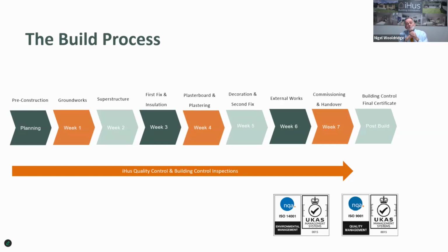green credentials. You'll be very pleased to hear that at the bottom of that screen, you can see ISO 14001, ISO 9001, and you can see that we've UKAS as well. That's to prove our credentials for building and our credentials for building regulations. You probably cannot find a better insulated home than what we produce. To give you those in number context, remember I said 0.28. Well, your roof space is 0.18, living space 0.15, and floor space 0.18. So we're over-engineered to the standard Build UK rules, which is a good point for our customers.